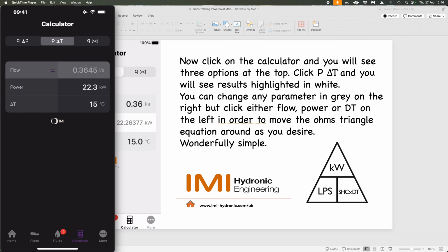But again, we can play around with it. So we want to now make this, for argument's sake, a low temperature system. And if you remember, we insulated the loft, we changed some windows in that calculation, and we got that 22.3, and with MVHR fitted as well, we got that down to just over 6 kilowatts. So it's about 6.1 kilowatts, I think, if I remember rightly. But that's at DT5, if we're going to put a heat pump in.